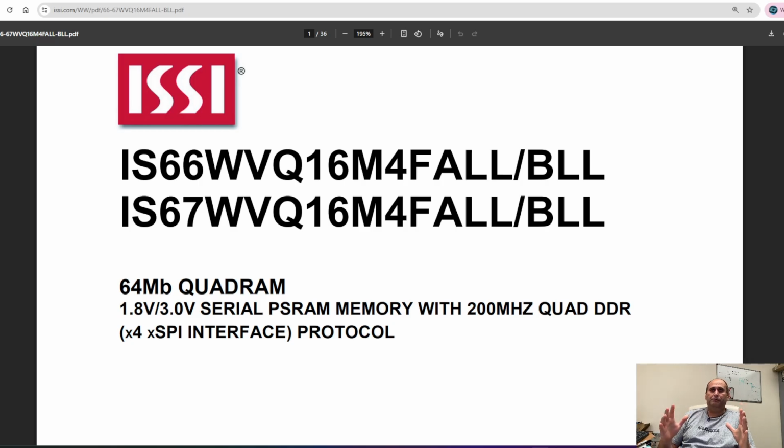A video controller continuously reads the video data from the RAM with the same cadence. Why? Because you can't afford to stop the display, because the image will tear. So you need to keep reading, and you need to make sure you sustain that. So everything comes down to the pixel clock. Let's say for HD, you have a 148 megahertz pixel clock.